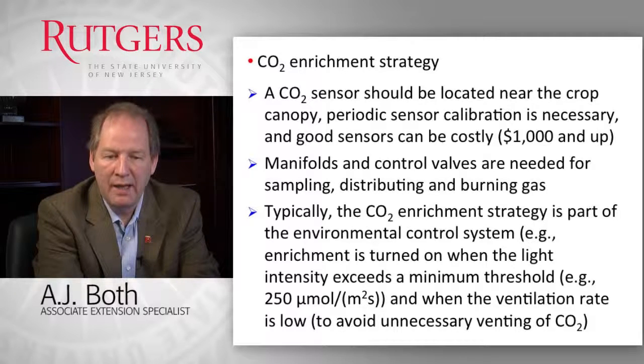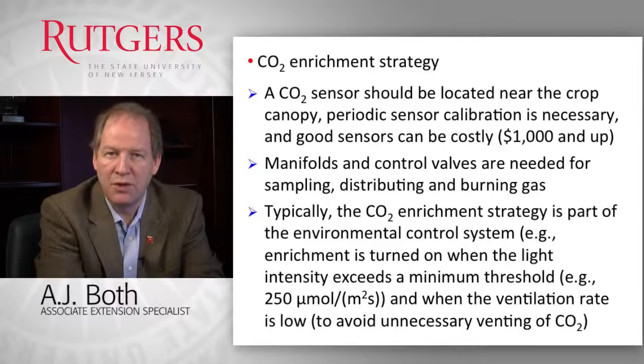And that is the way it typically works. We measure the environment, we look at light conditions, we look at other conditions, and we know the CO2 concentration. Depending on the target set points, we can then decide to, for example, increase the lighting, but also increase the CO2 concentration, because we know that the CO2 concentration is low when we are trying the light, and if we don't add CO2, that will result in conditions that do not result in the best plant growth and development that we were looking for.